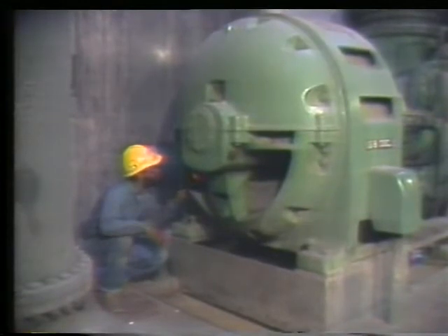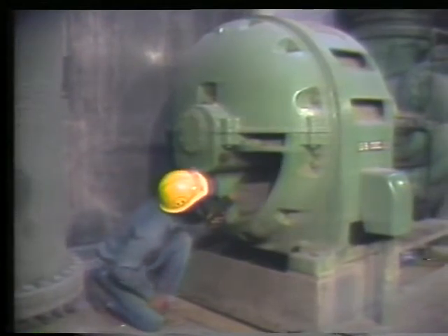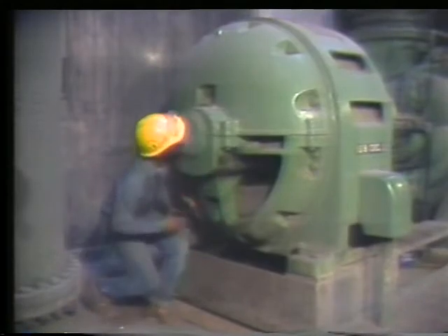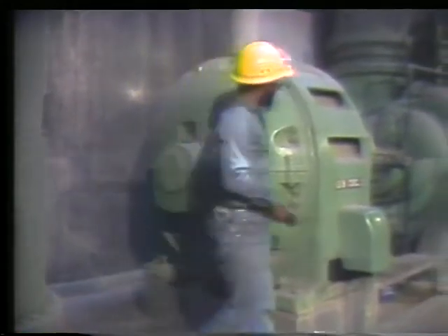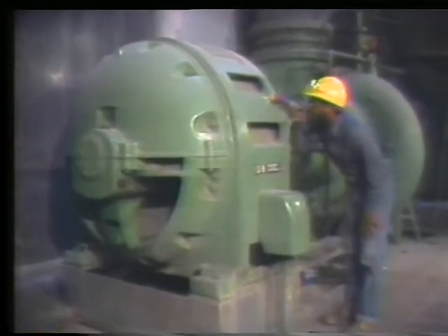Try to use all your senses to their best advantage. Visually inspect the motor for any loose or broken parts. Check the air vents for dirt or grease or other obstructions to the motor's ventilation. If a blockage is found, the motor must be shut down and the blockage removed.